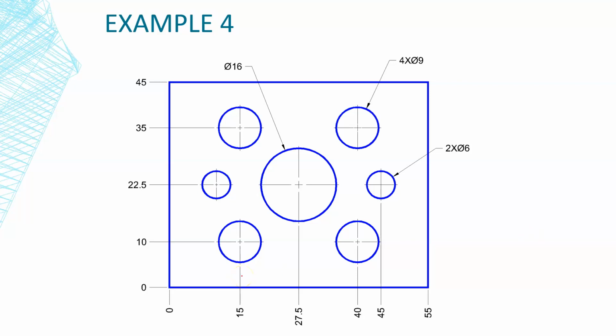Okay, so welcome back to this video, and if you've never seen this dimensioning style before, it's known as datum dimensioning. One great thing about it is that it clearly defines where 0, 0 is. So it's going to make this drawing super easy, and you can see that right here at this location is where my 0, 0 is going to be. Alright, so that's where we're going to start and kind of create and build everything from.